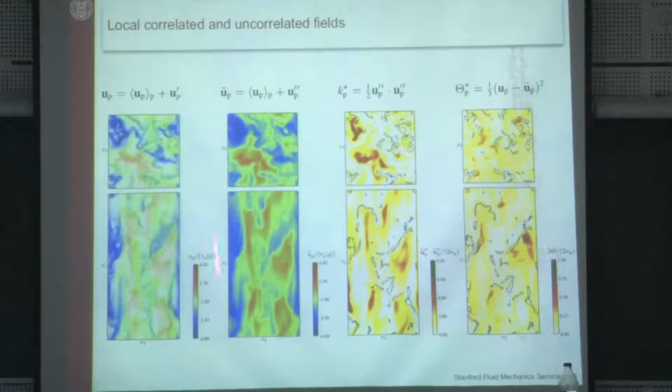I can now measure the amount of agitation that is in this. I can compute the amount of, if you will, TKE associated with this Eulerian velocity, and that looks like this. But in the same way, I can look at the difference between these two and measure the amount of fluctuation that's contained in between these two.